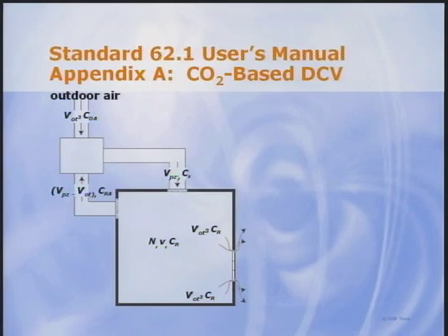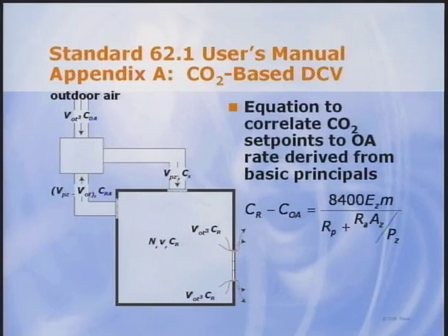Using basic principles, an equation is developed that correlates differential CO2 concentration, that's the difference between the indoor and outdoor concentrations, to the outdoor air ventilation rate. I'll discuss the equation in more detail later.